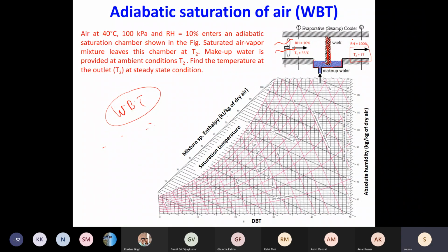So the entire mass transport process can be seen as analogous to the heat transfer process. In heat transfer, the driving potential is temperature difference. Here it is the difference in omega: omega incoming and omega of air just close to this wicking material. Okay, so this is the driving potential, but you also have area, which is an important factor.